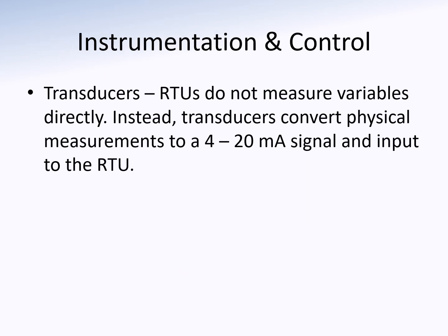We have transducers, and those are going to take that measurement from your primary instruments, run it through a 4 to 20 milliamp signal, and that's going to convert that into a measurable readout for you, or input, and send that through the remote terminal unit.